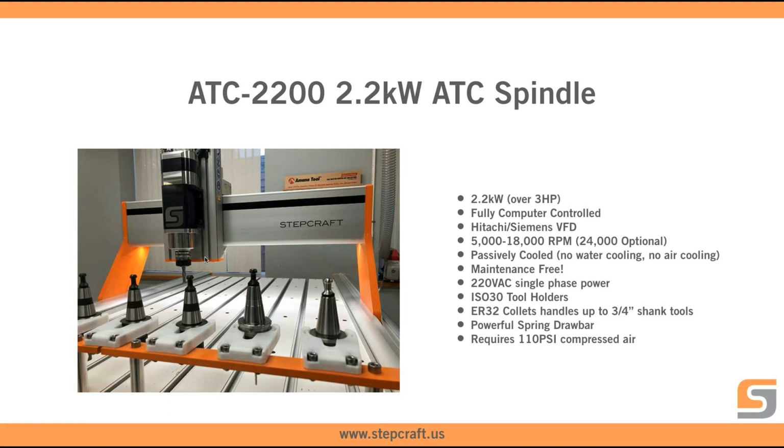A lot of times, say I'm doing a cribbage board and it's got hundreds of holes in it, instead of using an end mill, which is not the best tool for vertical hole drilling, I'll put in an 1/8 inch or whatever size drill I need, get a collet to match it, and put it in the machine. When you're drilling holes, to drill at 18,000 RPM is crazy, and your bits won't last that long. They'll dull out pretty fast, and you develop a lot of unnecessary heat. So when you turn the RPM down, as low as 2,500, it's great for drilling.